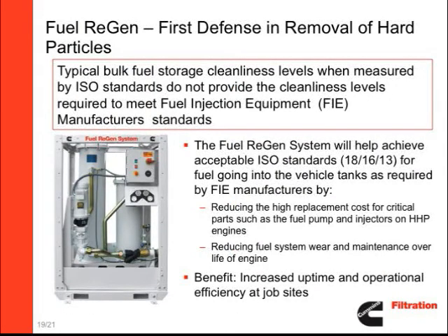We've discussed the importance of fuel island filtration. The FuelRegen is the first line of defense for hard particle removal. Typical bulk fuel storage cleanliness levels, when measured by ISO standards, do not provide the cleanliness levels required to meet fuel injection equipment (FIE) manufacturers' standards.